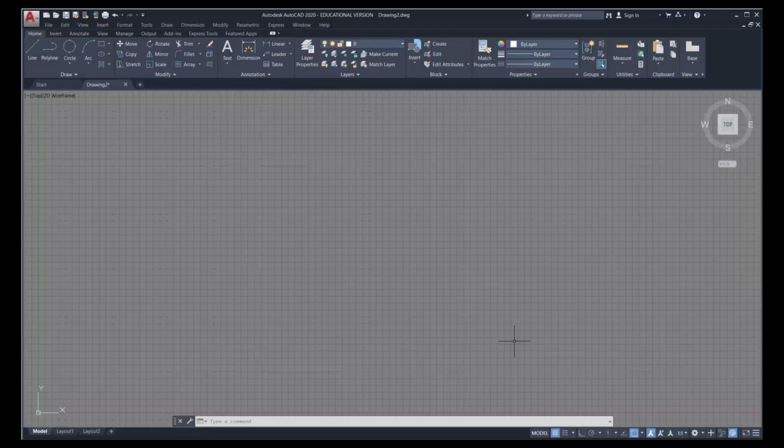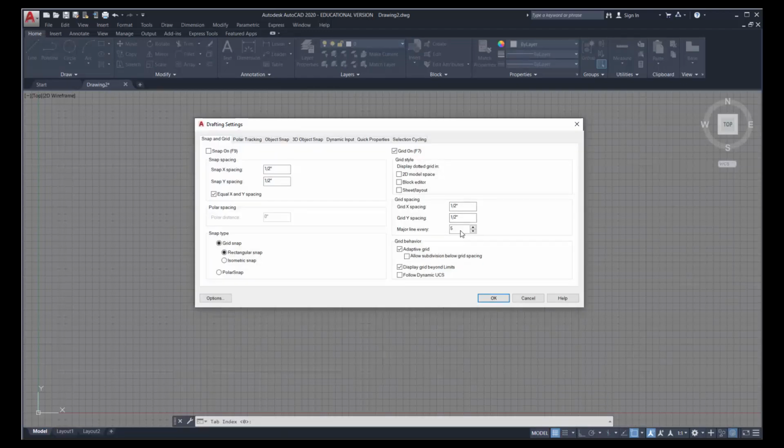Let's set up our display grid. So I'm going to go down into our drawing aids and click on the arrow beside the grid and change the snap function settings. Now for 20 feet, a grid spacing of a 1/2 an inch is really small. So what may be a bit more reasonable in the beginning here is something at about a 6-inch interval. Remove the adaptive and the display grid. Select OK.